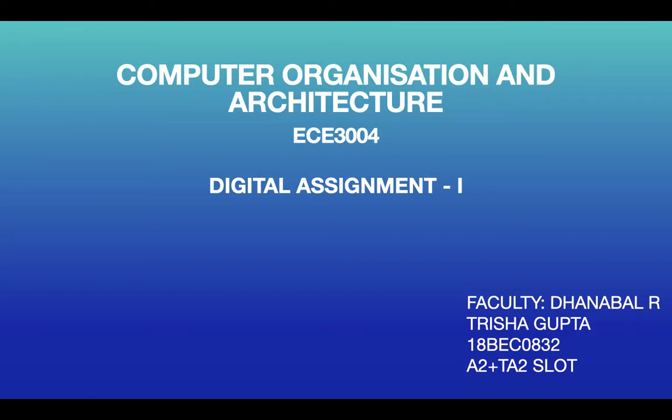I have chosen ESP32 developed by Shanghai-based Espressif Systems as the microcontroller. It was launched in 2016. It is an advanced microcontroller, cost-effective, and one of the few microcontrollers with rare features like DAC, integrated Wi-Fi and Bluetooth, two high-speed computing cores, which is Xtensa LX6, and an integrated ISP, image signal processor. This makes it ideal for Internet of Things and digital image processing.